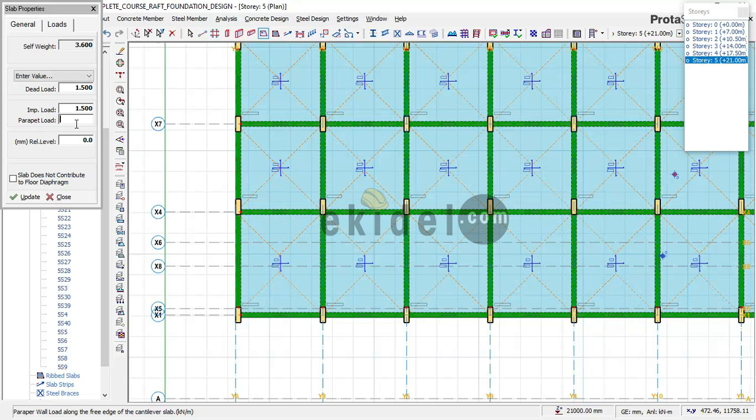So if I am designing for a cantilever, or let me say a balcony slab, and what is sitting at the edge of the cantilever is an iron rail or aluminum rail, I simply use a factored cantilever load of 3.5, because those aluminum or iron rails are hollow pipes and they don't have much weight. So I factor out my value to be 3.5. Most times I use 3.25. That is, 3.25 is my minimum and 3.5 is my maximum.